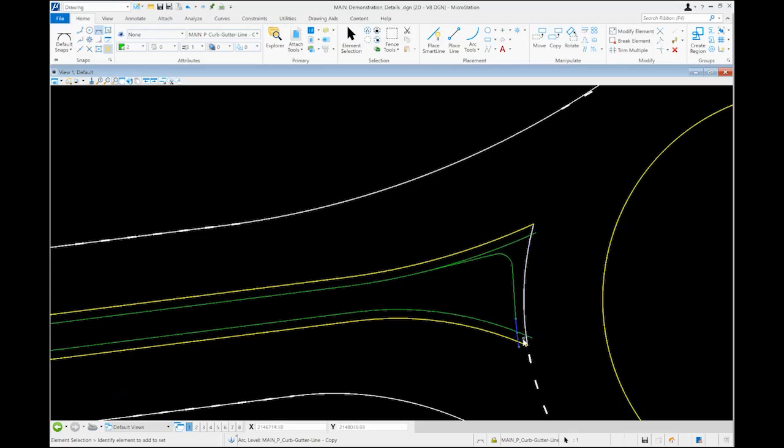So for this particular example, I'm actually going to remove that piece so that we end up with fewer inflection points along that curb line. We're just going to put our nose directly between this tangent and the 2-foot offset on the approach side. I'm going to use a little smaller 1-foot radius on this nose.